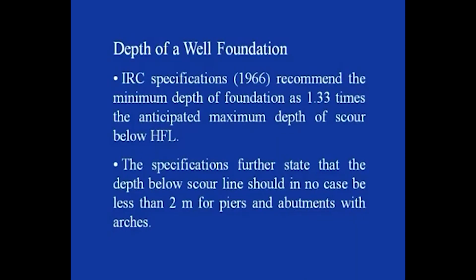The IRC specifications recommend the minimum depth of foundation as 1.33 times the anticipated maximum depth of scour below HFL. Further, the specification states that the depth below the scour line should in no case be less than 2 meters for piers and abutments with arches. So we need to consider these two criteria, and whichever gives the larger grip length, we need to provide that grip length.